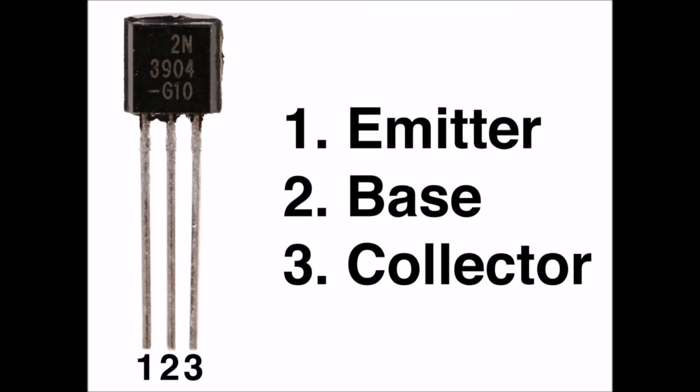Gain versus frequency. A bipolar transistor exhibits an amplification factor, gain, that decreases as the signal frequency increases. Some bipolar transistors can amplify effectively at frequencies up to only a few megahertz. Other devices can work into the gigahertz range. The maximum operating frequency for a particular bipolar transistor depends on the capacitances of the PN junction inside the device. A low junction capacitance value translates into a high maximum usable frequency.